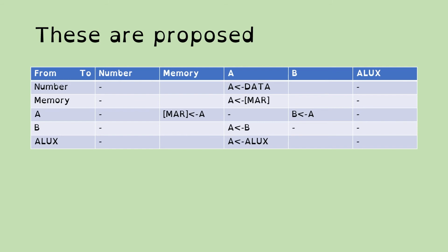The other thing to add here is that we've got something in square brackets, and that means not the actual data that's in MAR, the memory address register, but the data in the location indicated by MAR.